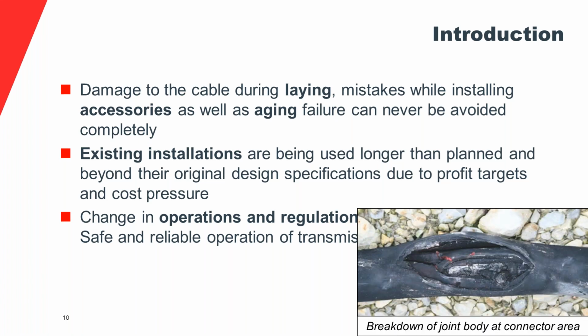And at the end of the day, this is what we're talking about. If you have a cable failure of one of these longer faults that take a longer time to actually show themselves, then this is one of the results. You can see the splice body there near the connector, and you had a breakdown there that was due to a fault that, for instance, would have passed the VLF test, because it takes so much time to actually show itself that a 1-hour test is not going to show it. Actually, no initial withstand test would show it, and then over time, it would come to this fault.